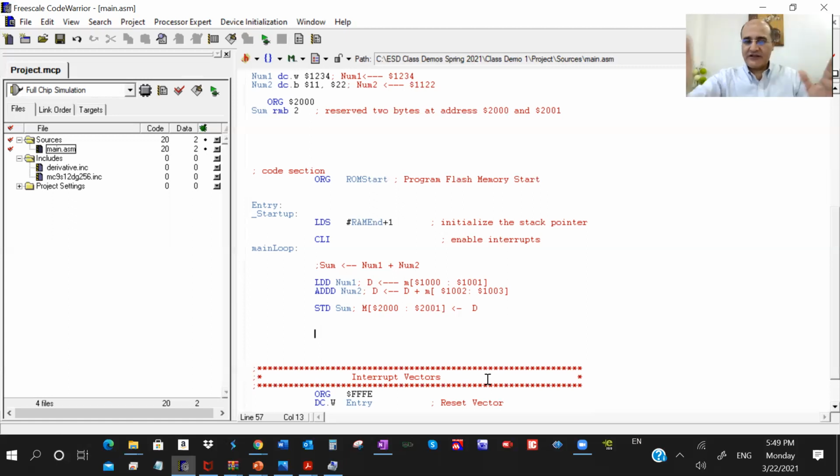So in embedded systems, we always should have an infinite loop, doing something over and over again. Read the sensor, convert the reading into a physical meaning representing temperature, check if the temperature is above or greater than the value I read from the remote control, decide to turn on the compressor or turn off the compressor, then do what?